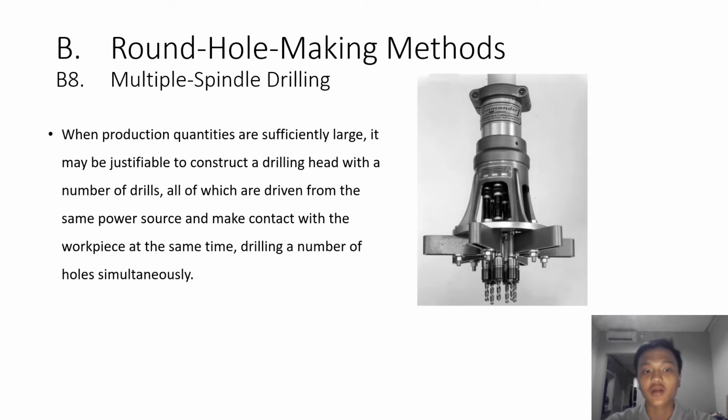Multiple spindle drilling. When production quantities are sufficiently large, it may be justifiable to construct a drilling head with a number of drills, all of which are driven from the same power source and make contact with the workpiece at the same time, drilling a number of holes simultaneously.